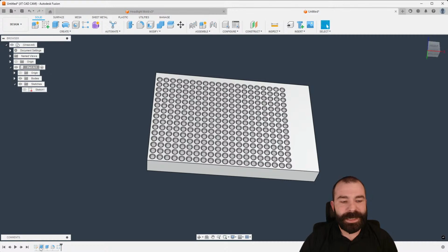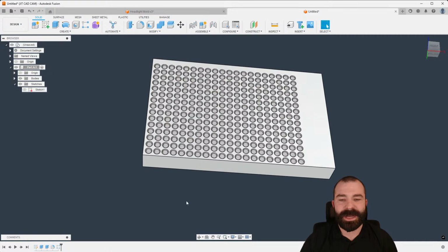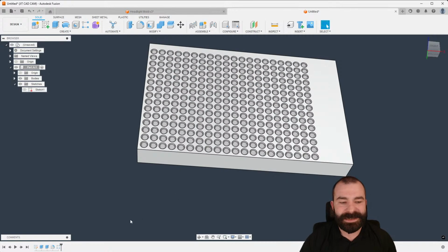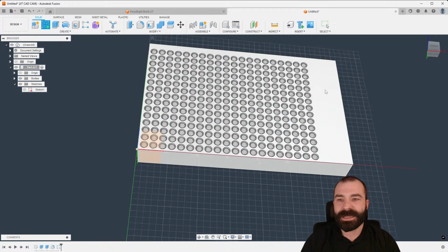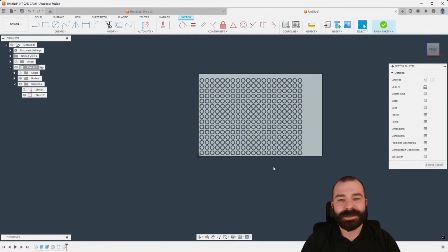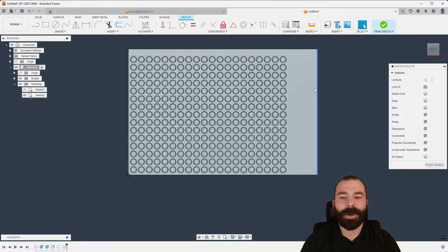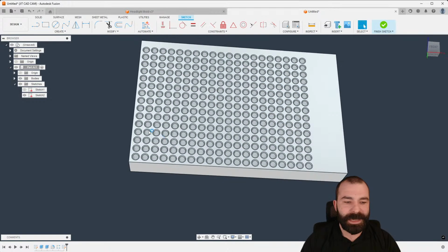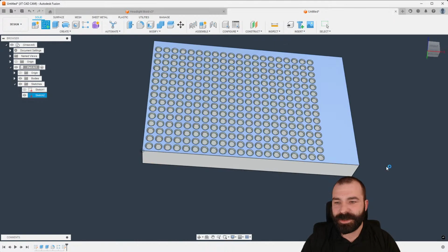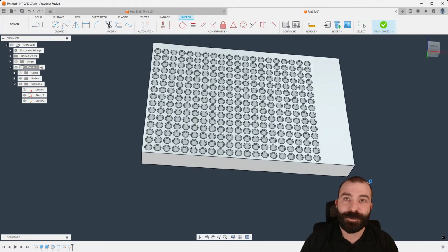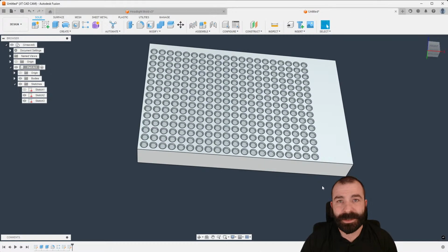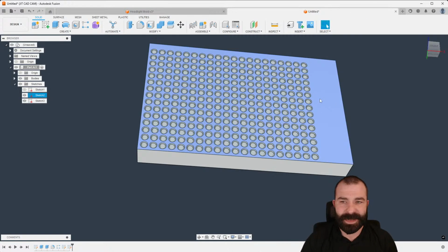Now, where we get into more issues here is, as you guys are seeing, the next thing I tend to see is if somebody wants to add more detail to the same plane, they start to create new sketches. There's a time and place for this, right? But in this case, every time I go in and add a sketch, I am lowering the performance on the design side because we're dealing with lines and arcs and those calculations.